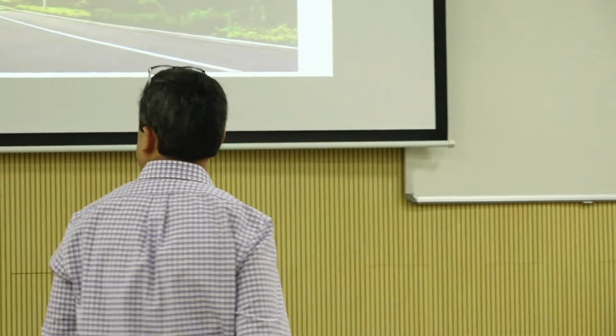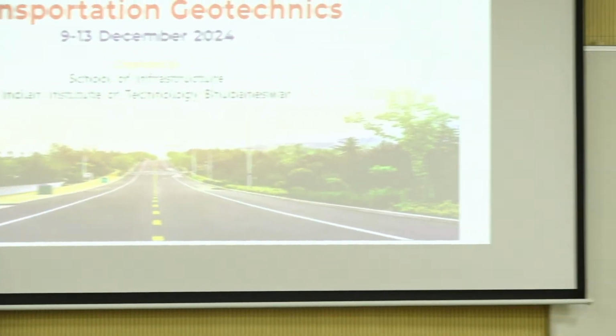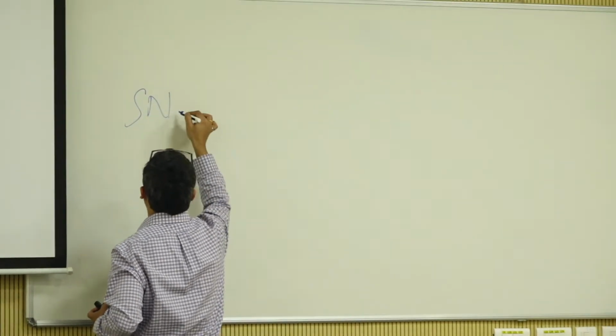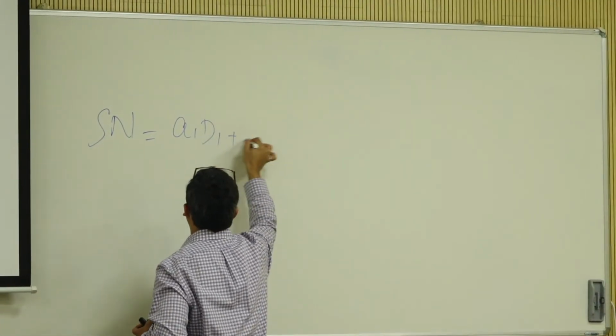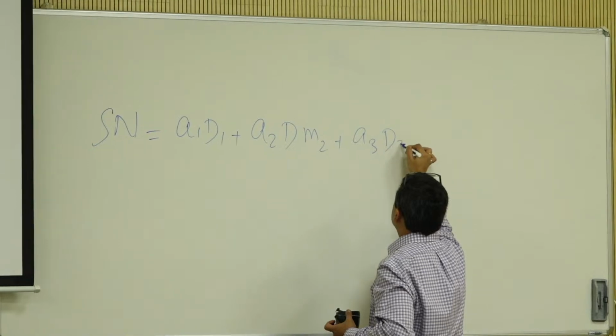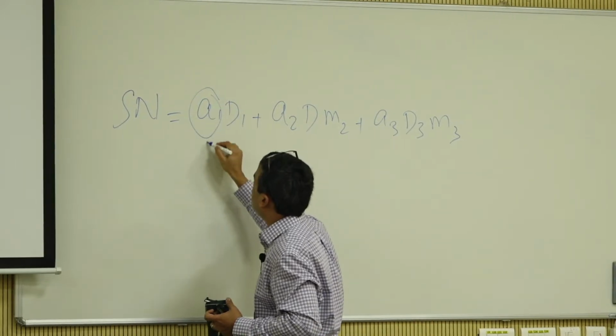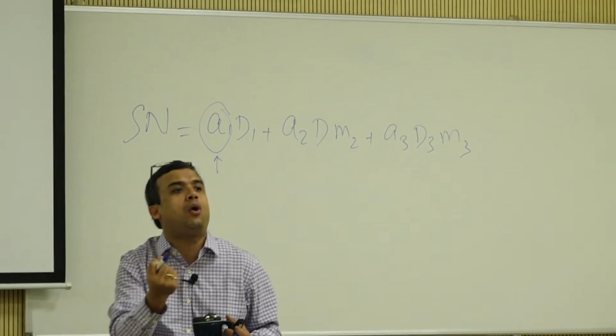If you go into empirical design, in AASHTO, it is all based on something called the structural number. So a structural number is basically... who remembers the formula? Others, come on, PhDs. SN equal to a1D1... There you go. Okay, plus a3D3m3. I can't go over all of this right now. So a1 is called the structural coefficient. It's basically how good your material is.